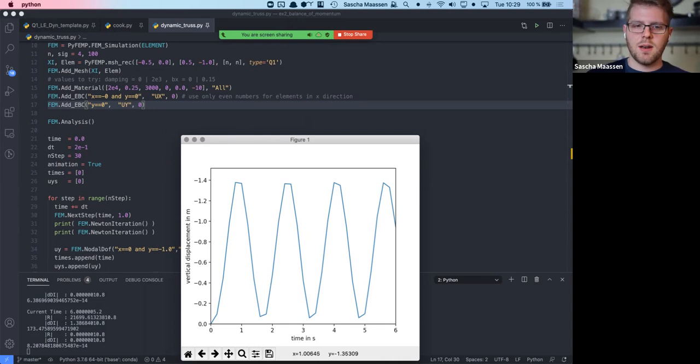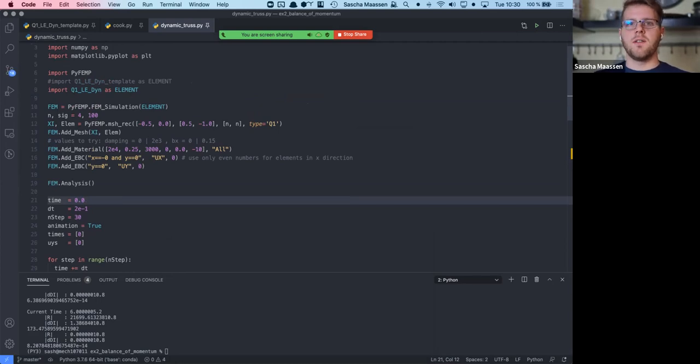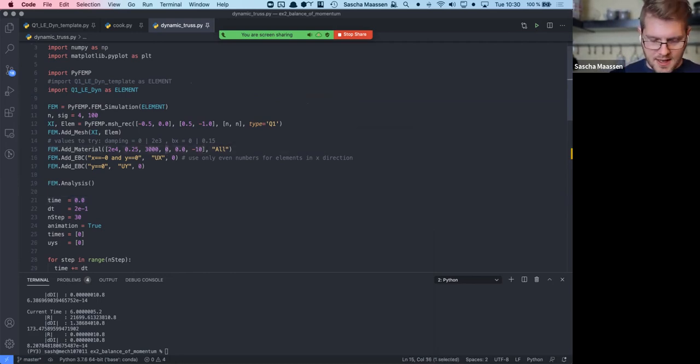Here we see as one important aspect that we have exactly the oscillation that we observe on the single mass oscillator, and that this will continue, let's say, for a long time. Because of numerical effects, there might be some damping involved, but it's not visible in this time span here. So this is what to expect from this dynamic analysis. There is one modification, because we have included now also our viscoelastic material law, which was not active until now, because this parameter over here, once more, we will go through this in a second, is actually our damping parameter, which was set to 0.